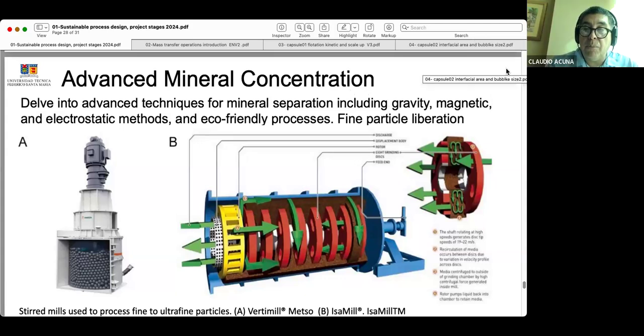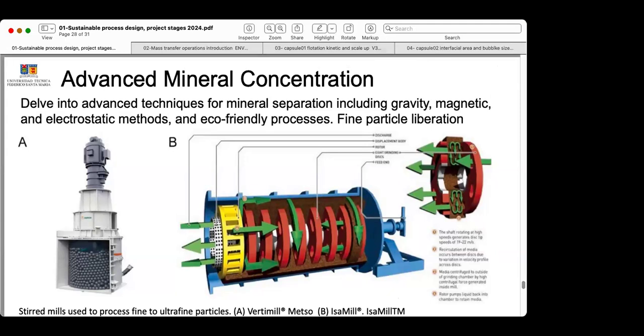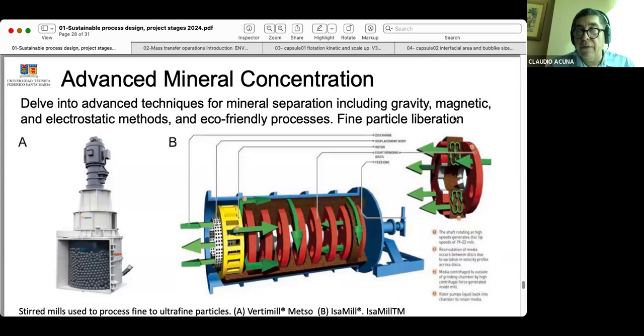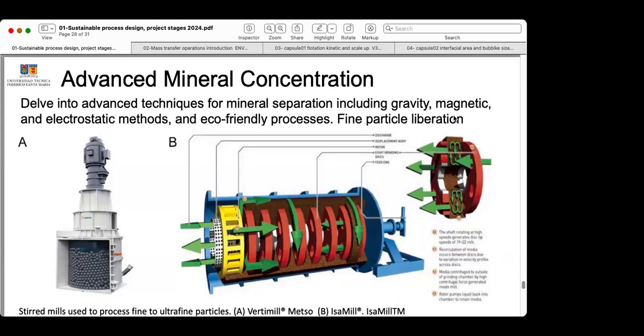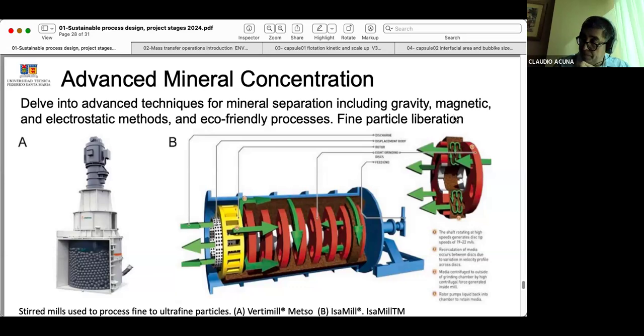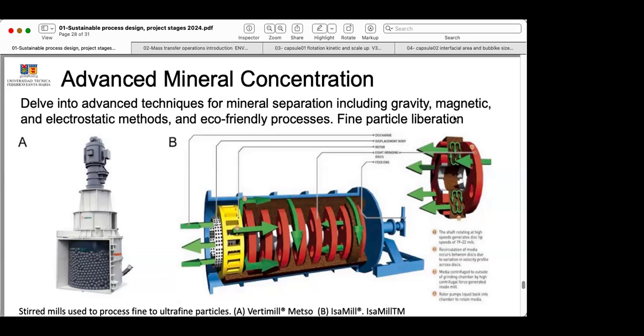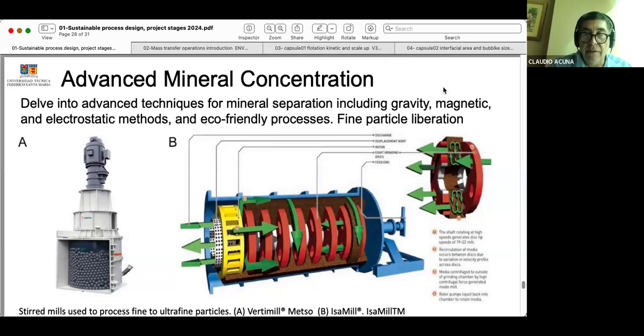I'm saying in a concentration process, you have crushing, grinding, then flotation, and also you have an intermediate operation of grinding. Why do we need an intermediate grinding operation? Any idea from the process design point of view? For further liberation. Where? What stage of the circuit? You mean the regrinding? Yes, regrinding, which is basically in the flotation circuit before going to the cleaner, after the rougher and scavenger.